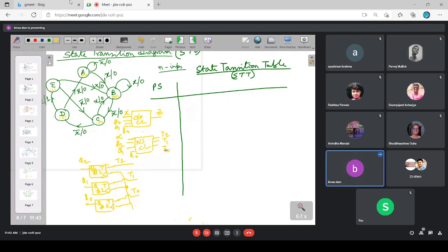Okay. Now you can understand why I have given the name next state information, not the next state. Will your T2, T1, T0 be the new Q2, Q1, Q0 value? No, sir. It is giving you some information about what my next Q2, Q1, Q0 values should be.